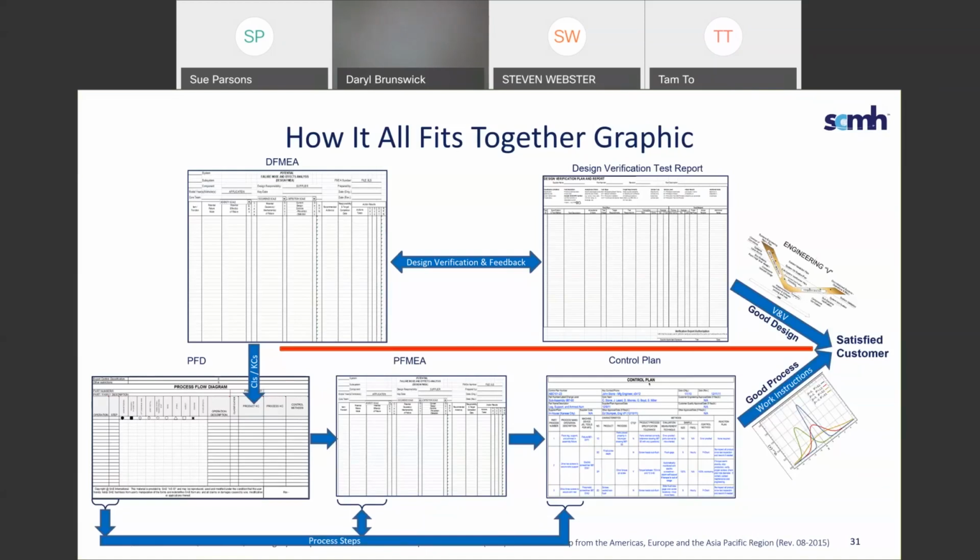And then your control plan has the same column on it. And it shows how you control that KC in your control plan, either by statistical process control, 100% inspection, or whatever. Every one of those forms has a classification column, which starts with the DFMEA going through the PFD to the PFMEA.